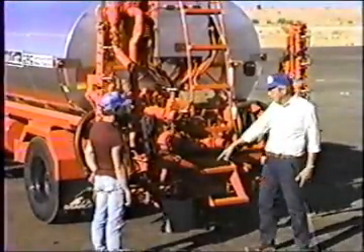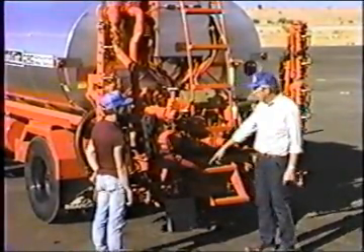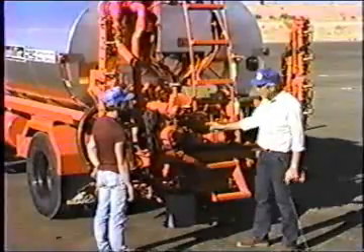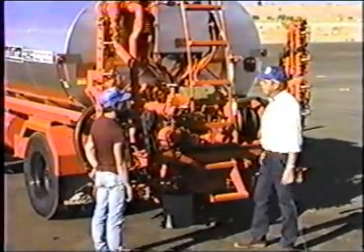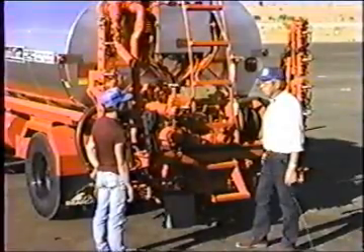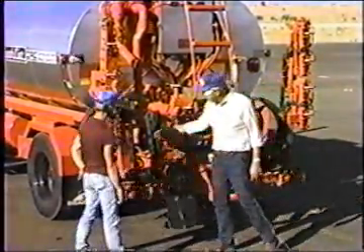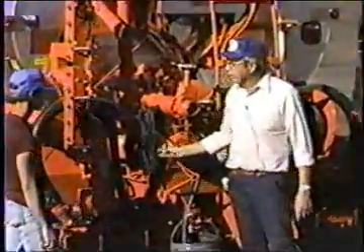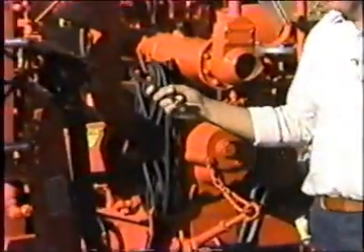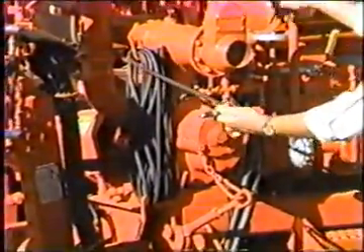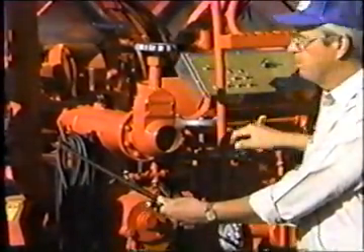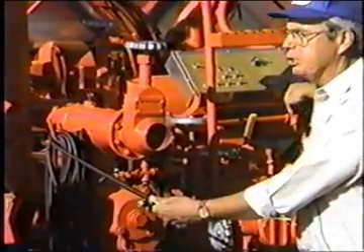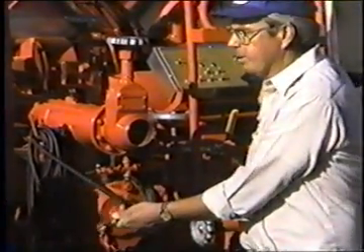We're circulating the bucket, out of the bucket, through the system, back into the bucket. I want to do that for 5 minutes. It doesn't matter how long you do it. It's the ideal time to use the most important piece of gear on the back of the truck. That's the washdown hose. There's 20 or 30 feet of hose here, and that's tied to the fuel pump. On a diesel burner truck such as this, the fuel pump is on the burner. Put the burner in the wash position, and this pumps fuel to wash it.